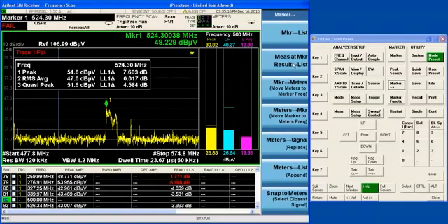So if I do that, then it will actually put that result in at the point where the current signal was. So it's in the list, and you can see that it's also showing me the delta to each limit line. And notice it's configured right now to use limit line 1 for all of the deltas, but I can actually go and configure each detector to use a different limit line, because sometimes I might want to have one limit for the peak detector and another limit for the quasi-peak detector.